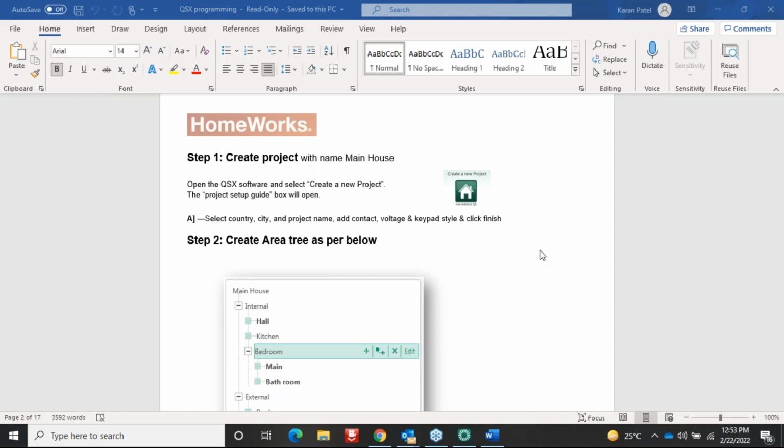You can use an old version, because when you transfer the program, the firmware will remain. The programming file is different from the firmware. Earlier, when you transferred the program, the software would auto upgrade the processor firmware. But now, as the processor is on cloud, the firmware is automatically updated, so you can use the old software for reprogramming of the system. Okay, thank you very much for the question.